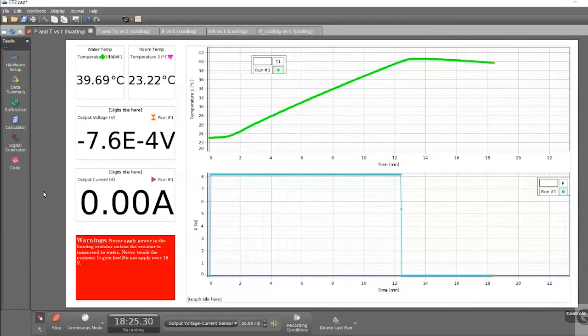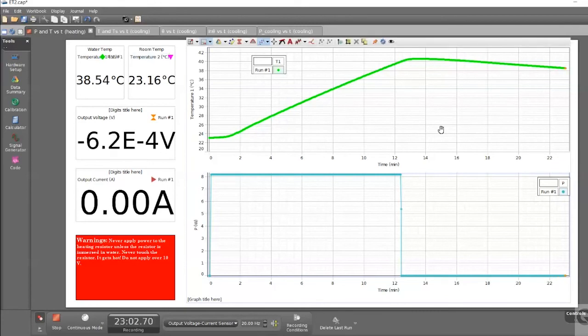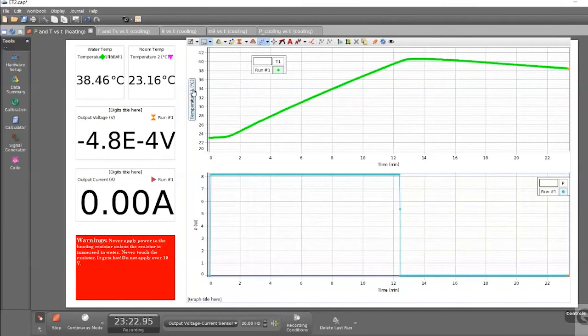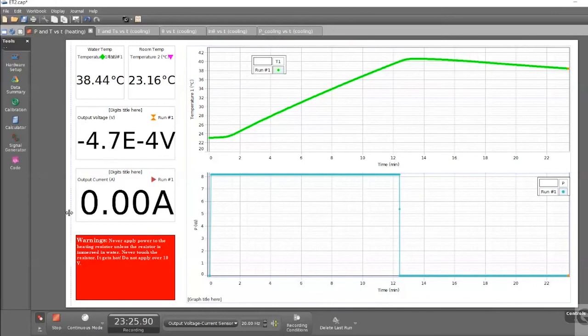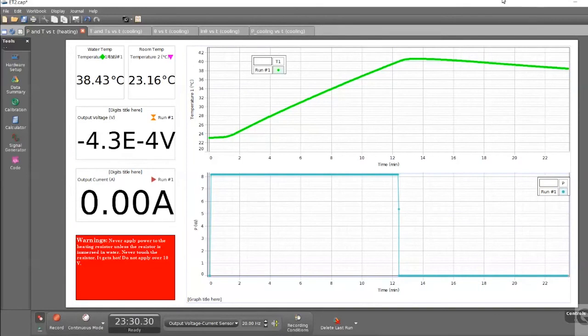You can see from the top graph, from temperature versus time, that the maximum temperature has been reached and the temperature is starting to drop gradually. It looks like it's linear, but in fact that is an exponential decay, approaching room temperature, the surrounding temperature, about 23 degrees. So that's going to take a very long time. So we're only doing it for 10 minutes. So we actually need to do a different graph of a log of the temperature difference versus time, not that one. Before we do that, we'll just get a couple of useful bits of information.